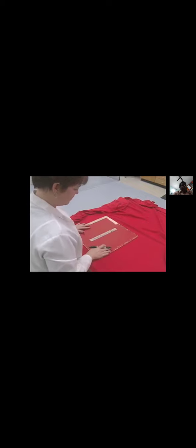The wale direction specimens will be marked and cut so that the long dimension of the template is parallel to the length direction of the fabric. Similarly, the course direction specimens are marked and cut with the long dimension parallel to the width direction of the fabric. After the specimens are cut out, each is folded in half lengthwise, forming a loop when the short edges are sewn together with a 0.5-inch seam. Then, benchmarks 5 inches apart are placed on the fabric in a central location on one side of the looped specimen. This marking creates the gauge length, the original distance.